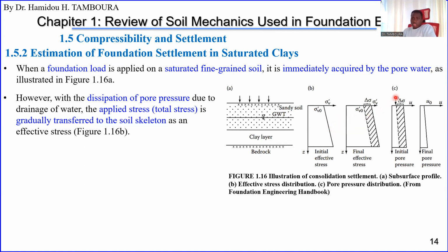And the pore water pressure will take some part of the load, and during the dissipation of the water, it will transfer that load to the soil skeleton, little by little, okay? As you can see here, for example, this is the initial pore water pressure, okay? So it means this is the total load that the water will take initially.